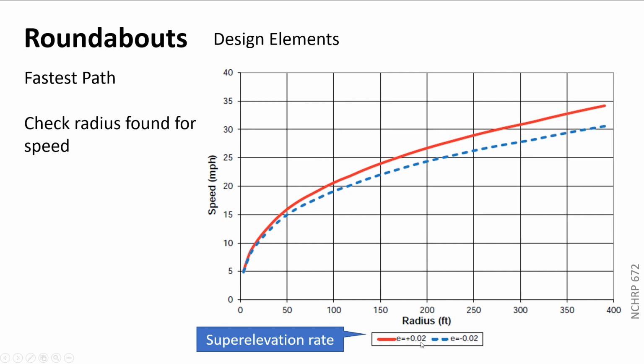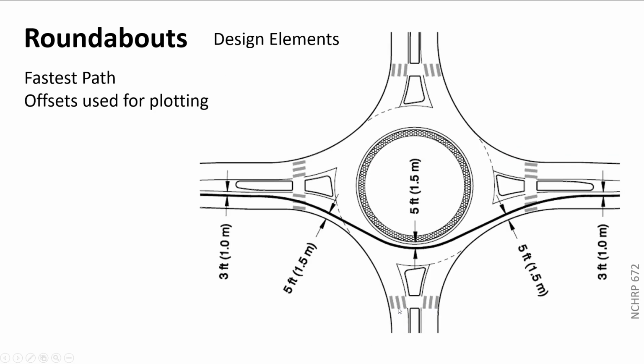And here's our super elevation, and the point is when we design these coming in, usually this roadway edge here is lower than that, so we're sloped outwards. So you've got a positive super elevation coming through that. But as you come around this curve, you're turning left, but the road is still usually falling to the outside. Not always. You don't have to do it that way, but usually it is, and it's falling outside. So that's a negative super elevation, and you come back to a positive super elevation.